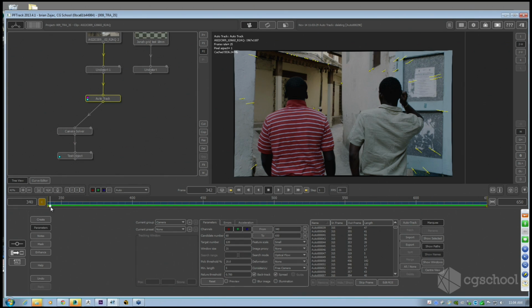You can either create a mask at the beginning and then auto track, and then it just doesn't take into account anything that's inside that mask or outside the mask. You can invert it. Or you can just track it and then go through and delete the points like I've been doing. For most of us in the studio, we prefer manually going through and deleting things.